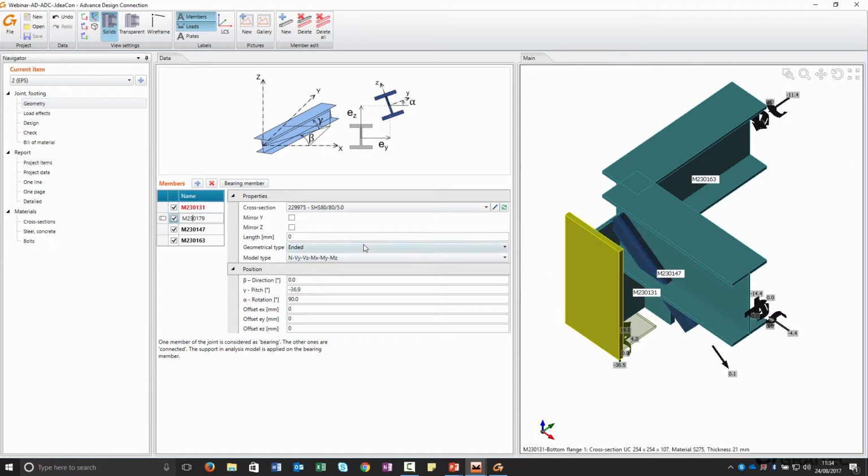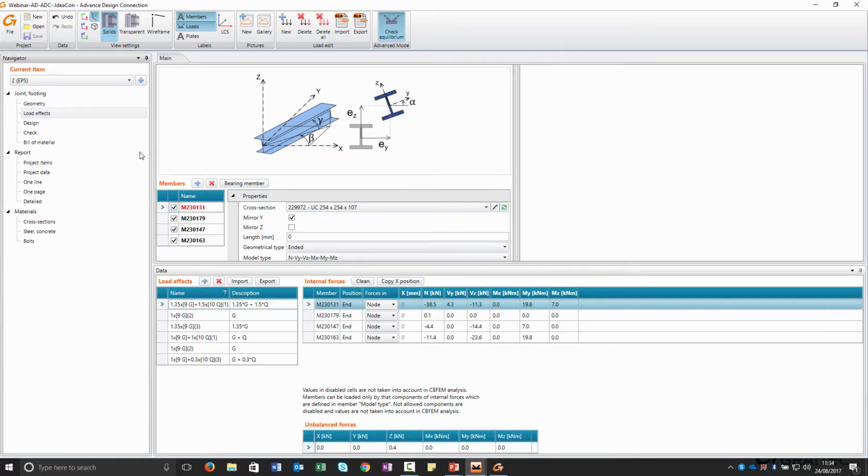this is the bracing, and as you can see there, the rotation I have set, and here I have my two beams with two different rotations. So as you can see, this is the rotation, the different rotation in X, Y, and Z axis. So here we saw all of them. And you can also set the rotation for this alpha rotation. Okay, good.